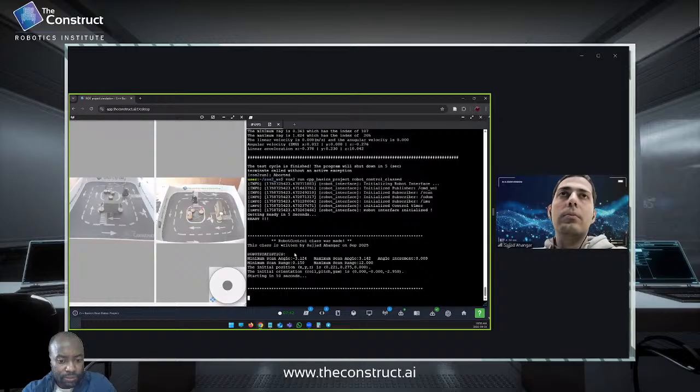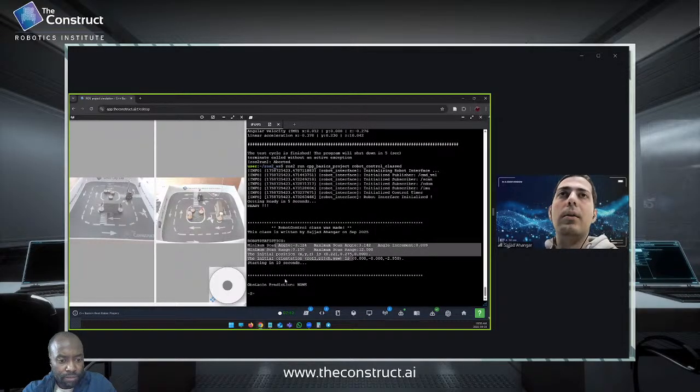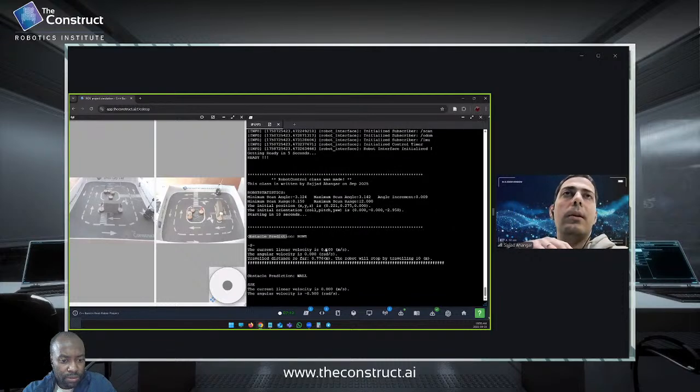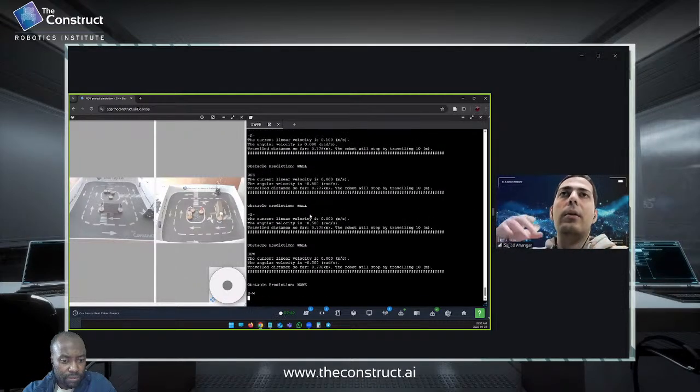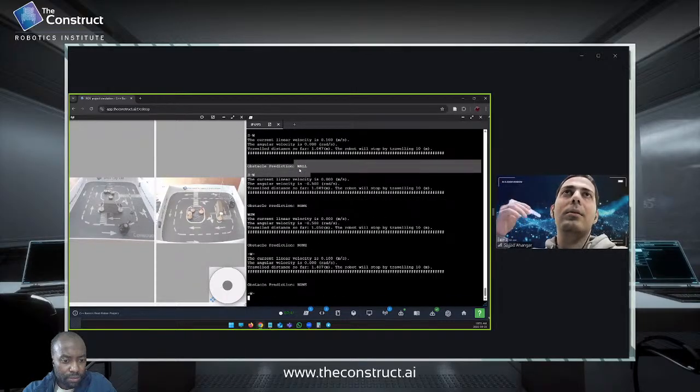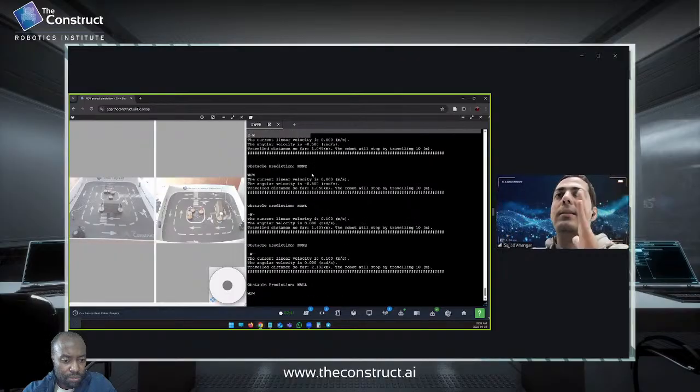Okay. Again, we should wait 10 seconds. I put this sleep time for reading this stuff. But yeah, it starts moving. You see there is no obstacle, and yes, it's going to the south, and it shows the linear velocity, which was 0.1, and there wasn't any angular velocity. It tries not to hit anything. And you see when it was near the wall, it predicted very well, actually. It understood there's a wall because more than half of that list was less than 0.3.